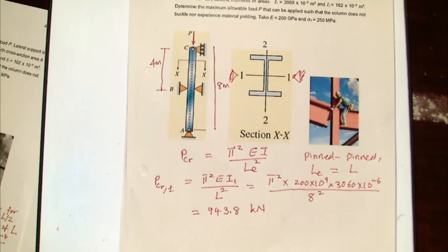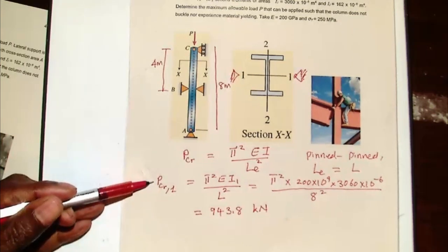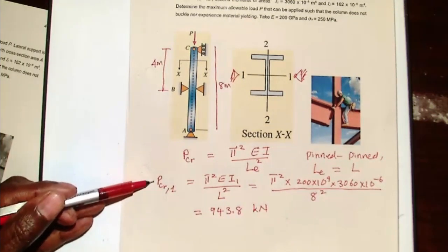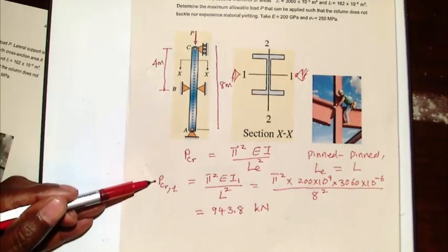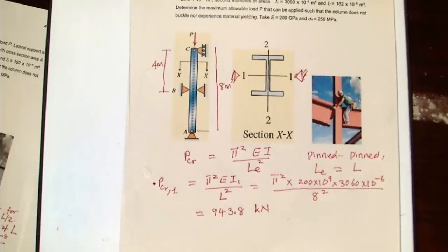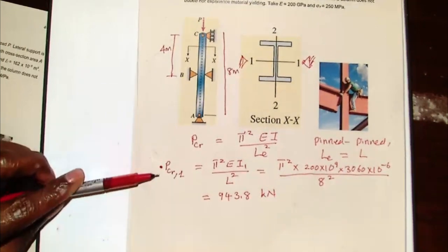You want the load you are applying when you are using the structure to be less than the buckling load, and also less than the load that will cause yielding, because you don't want yielding and you don't want buckling. There's nothing that says you have to make this more than the yielding.